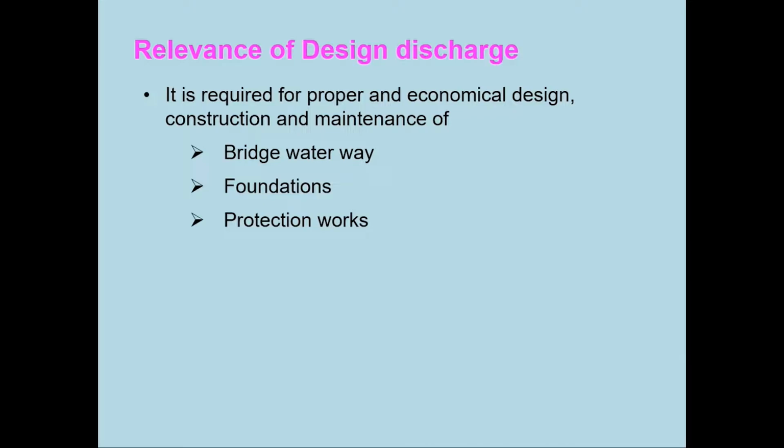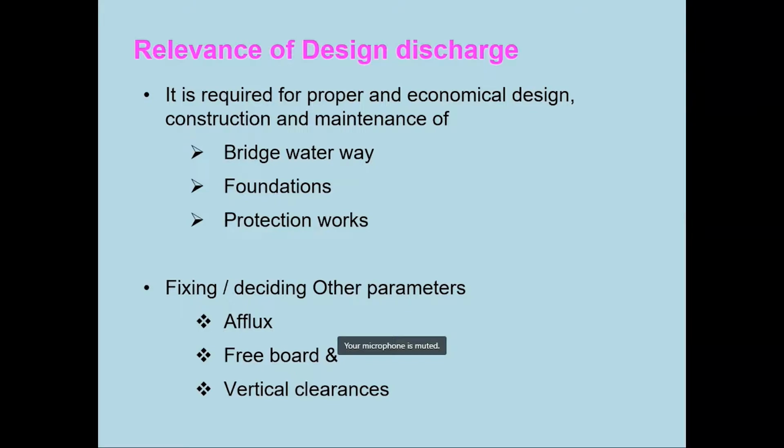So what is the relevance of the design? The design relevance is that it is required to decide the bridge waterway, and to decide the foundation and the protection work required for the bridge sites. For the foundation design, you will also require afflux, freeboard, and clearances.